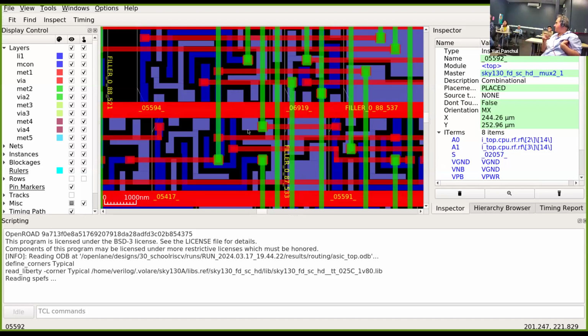Yes, everything, like floor plan, place and route, everything. It went through all stages: logic synthesis, static timing analysis, applying floor plan, placement, routing, and then it goes through a DRC check and various other checks. This placement and route didn't violate rules for how close wires can be to each other, and even some manufacturing effects, like the antenna effect and so on.